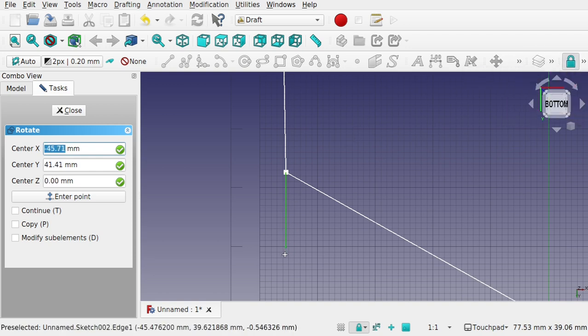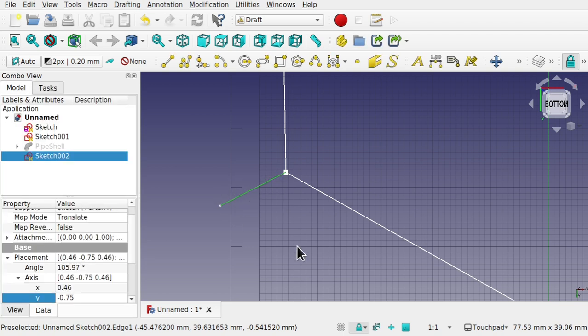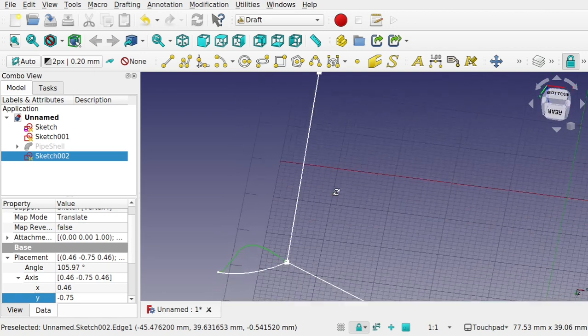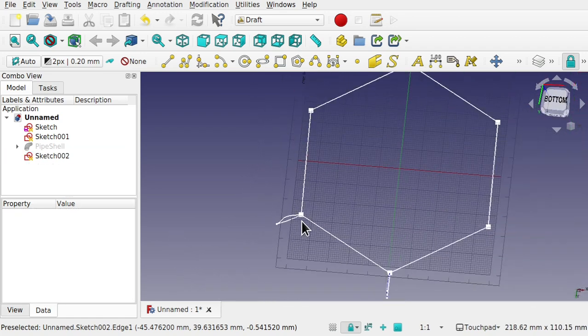That means this will snap. You can see where it's snapped to, that endpoint there, or it's snapped to that endpoint there. So we can click on that endpoint once. That's our pivot. And then we go to the end and click on that endpoint. See it's snapped there. We've got a little icon come up. That means we can move this like so, and we can move this to wherever we want, or type in 45 and that will move it to there. So press enter, or we can click the mouse or move this by hand and click. So there you go. So that's moved that. You can see if I click off of it, we've moved our profile now to there.